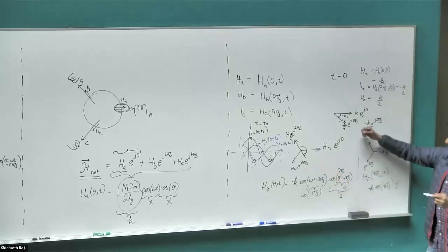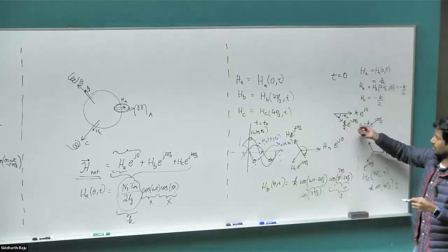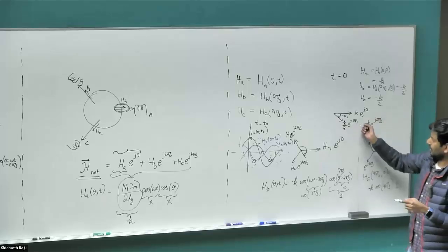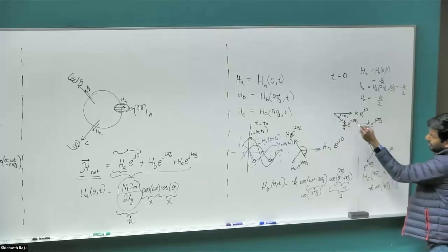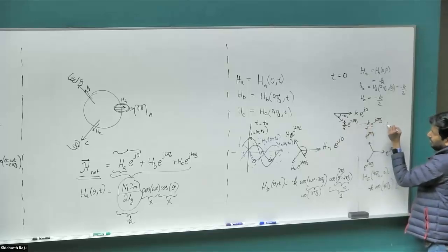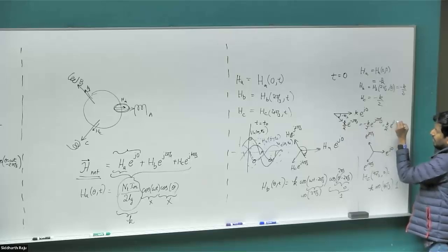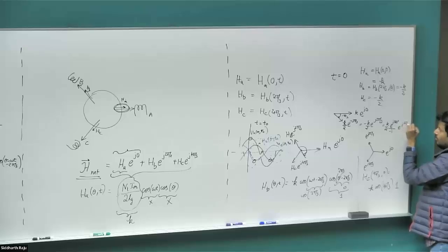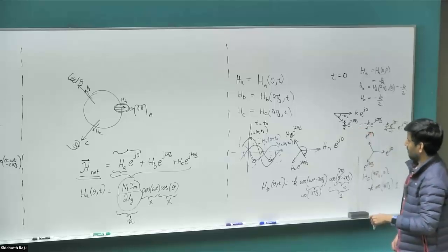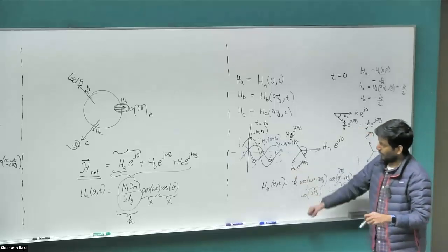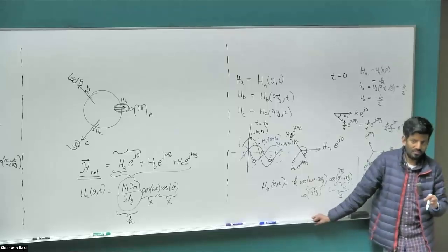So you typically don't want to put negative values on your vector, you would want to take it to the angles. So whatever the negative sign is here, I'm just taking it to the angle, which is the same as saying I'm multiplying it by k divided by 2 times e power j 180 degrees, right? This is -1 times e power j 2 pi by 3, e power j pi. So however you do it, you'll end up with e power negative j 2 pi by 3. Can somebody tell me where the vector for C will lie?